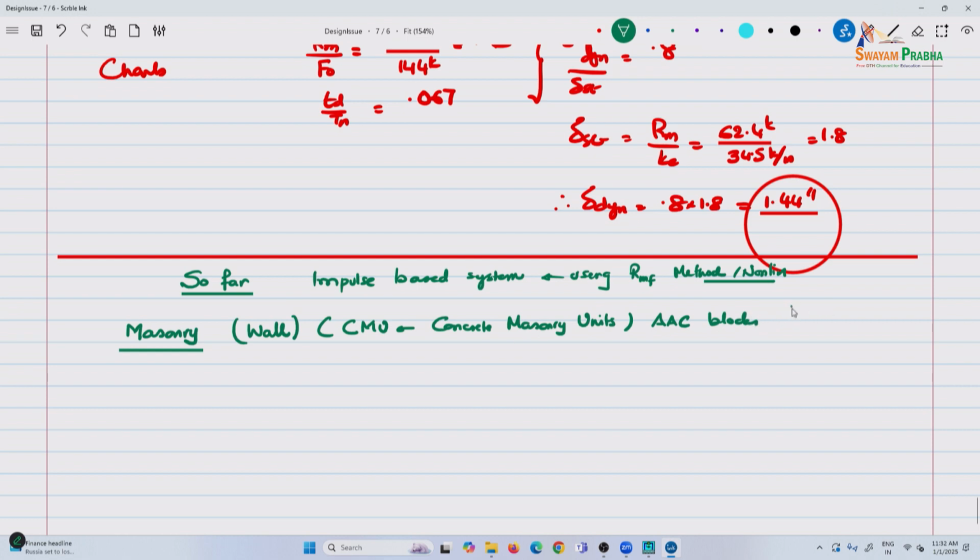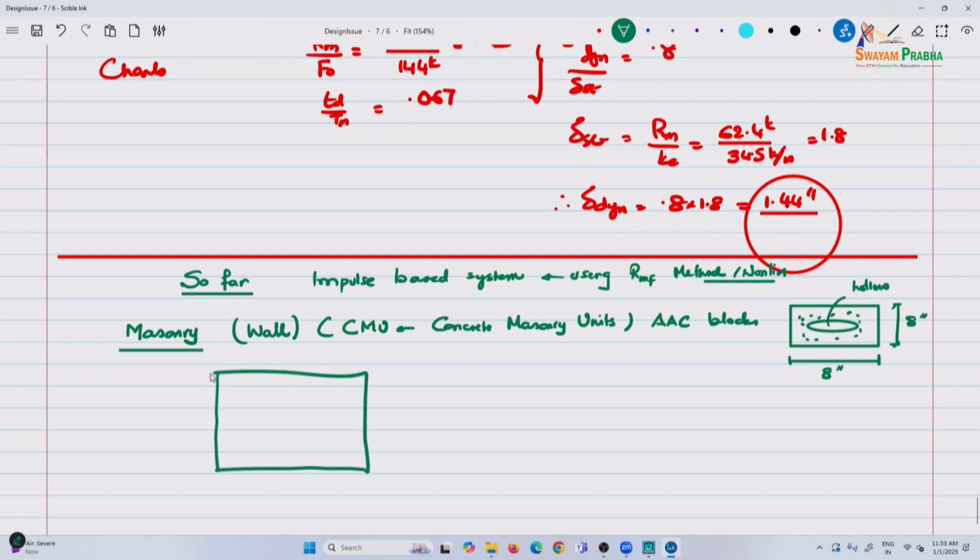So these blocks, if you see, this is a cross section and it will have a hole. This is the concrete block and the inner part is hollow. Typical blocks, these are nominal units, so these are 8 inches. We have 8-inch CMU blocks, and this is also 8 inches. So when you have a wall, and of course it depends on, these blocks would be something like this.